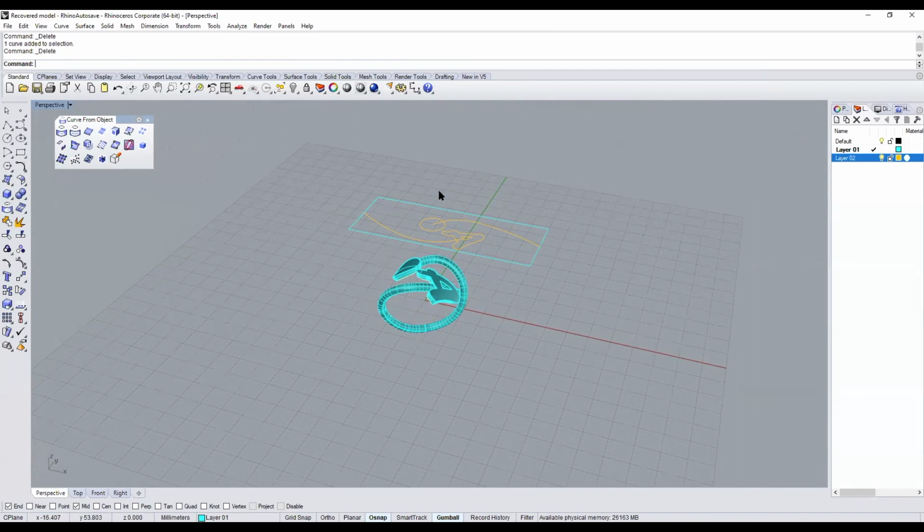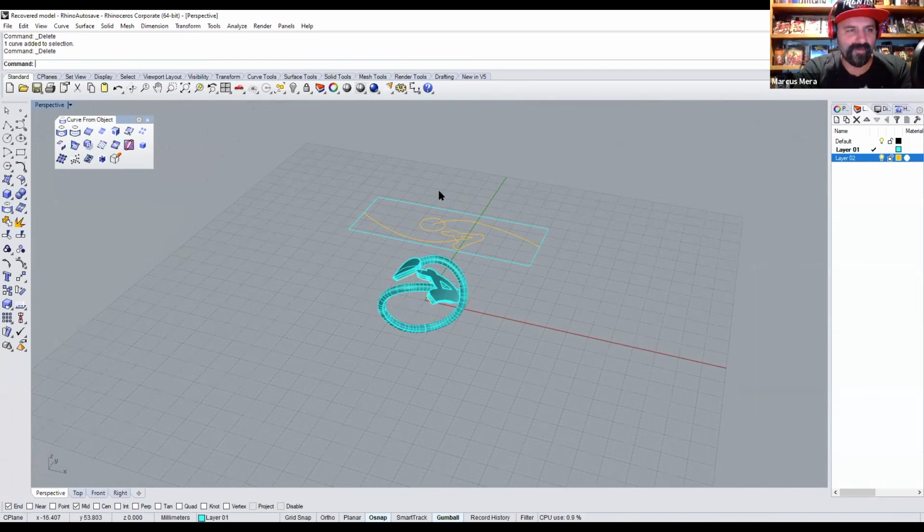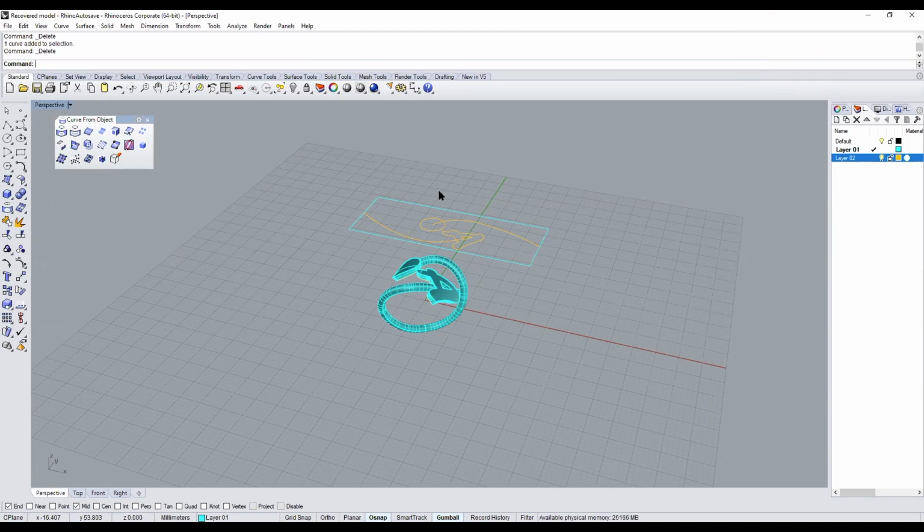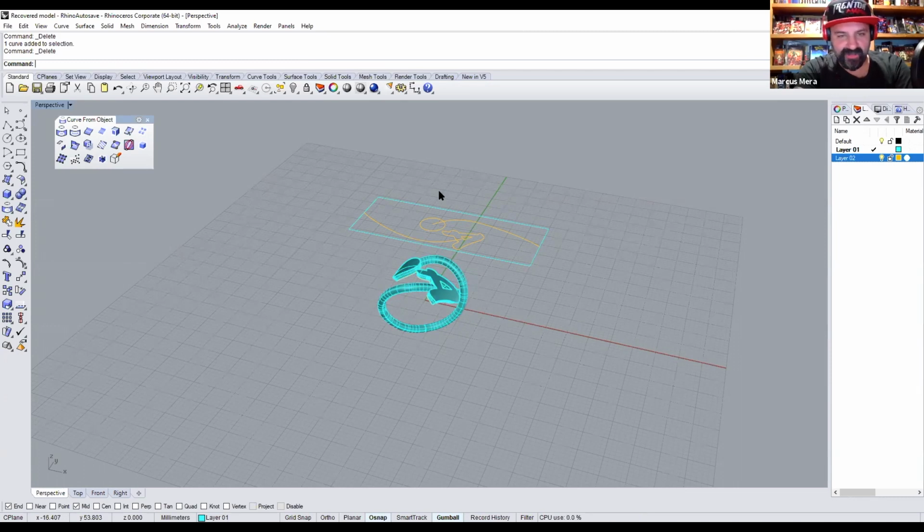And I'm really sorry, the project UV and the flow along surface are very similar commands, and I guess I got a little messed up there, but basically the gist of it is the same, and it works pretty well to design flat and then wrap around the object. And then you saw how I was cutting the surface and then offsetting it to create the solids. Yes. So that's a really cool thing to do.